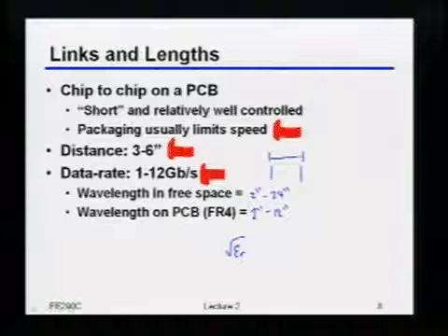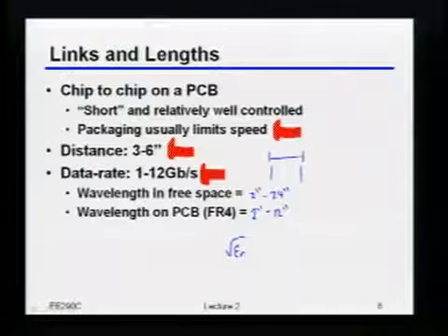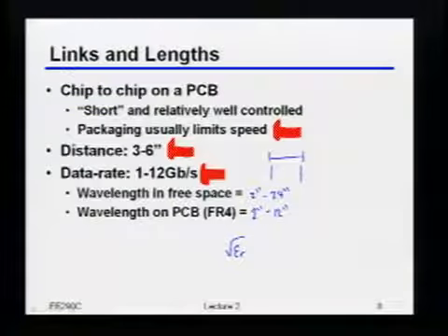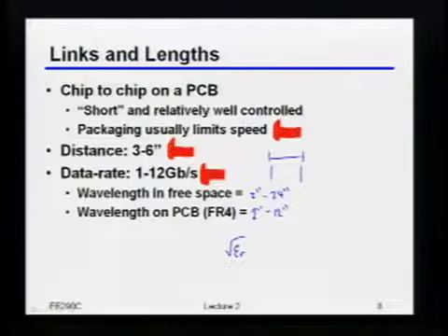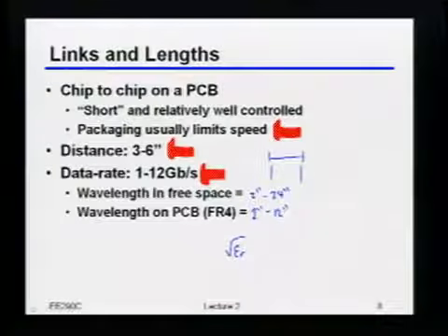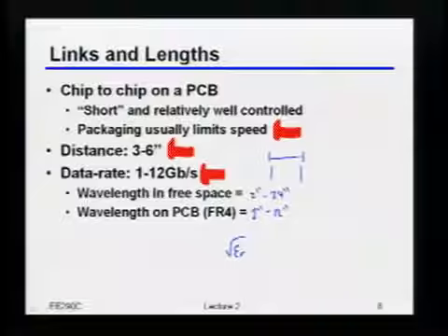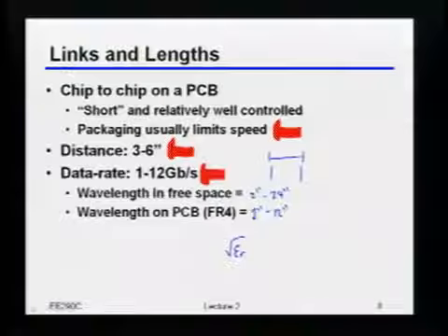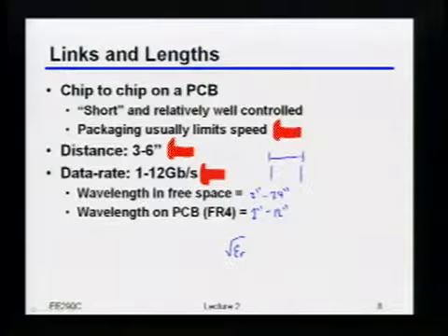So, what does this say? Can I treat things as being lumped or not? What do you guys think? Okay, maybe we'll take a vote. So who thinks this is all great? We're lumped, it's easy. Not lumped? Okay, of course. Now, why not? Well, the dimensions are not much less than lambda. Well, what do you usually mean by much less? Order of magnitude. Yeah, okay.